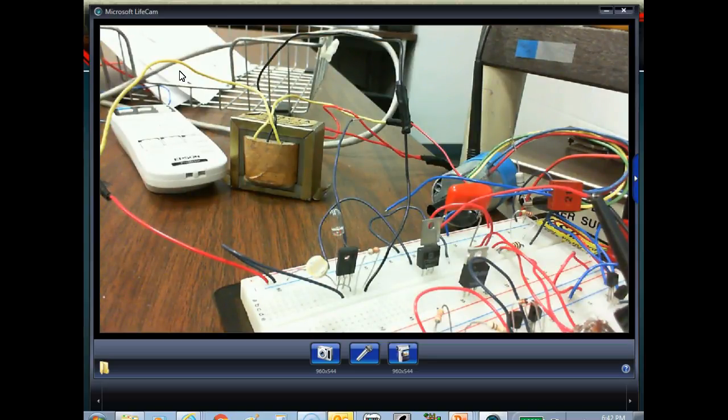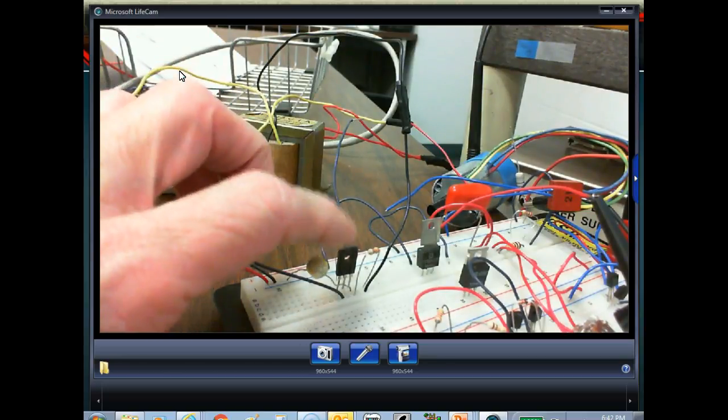That means you go out and take your radio apart and look at those outputs, they're going to be up against a heat sink, right? You understand? Because they're operating in the active region. And if they operate in an active region, they're going to drop a voltage. If you push a current through a voltage, you get what? You get heat.